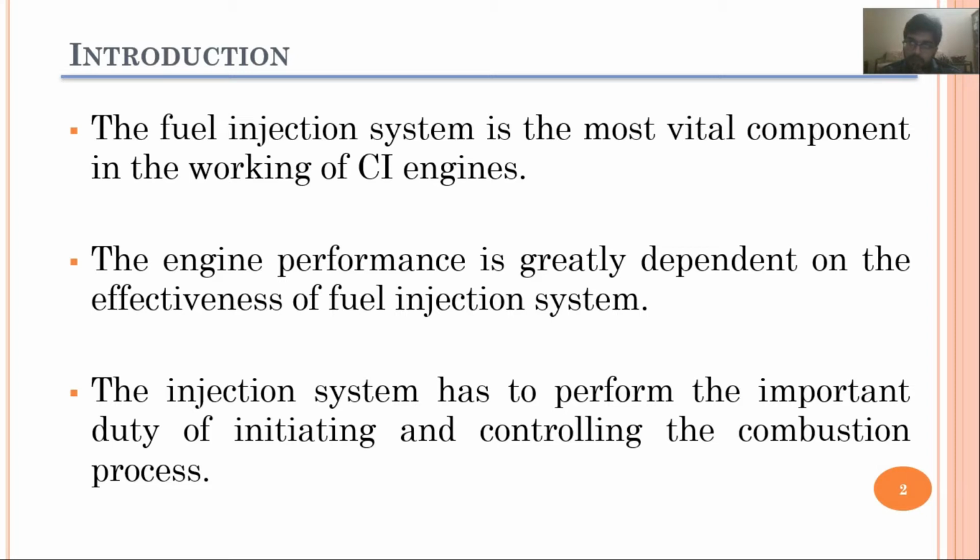It is because the fuel is being injected by this system. We are not preparing the air fuel mixture and sending it into the combustion chamber. We are only sending air in the combustion chamber, then fuel is sent separately at the end of compression stroke, and that is what the mechanical injection system is doing.